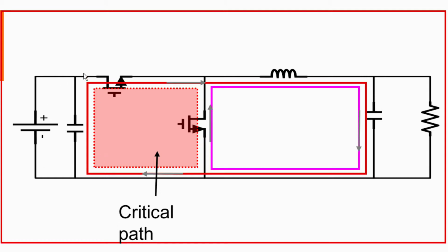So if this input capacitor doesn't bypass all the current, then you're going to get a pulsed current that goes down your line. That would be conducted noise directly onto your line. And if this loop is fairly large, then if you have a loop area and a current and you pulse it at a frequency, then you've made an antenna. And so then you're going to get radiated noise from this loop.